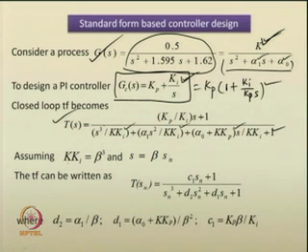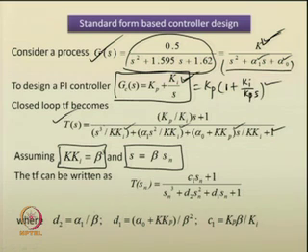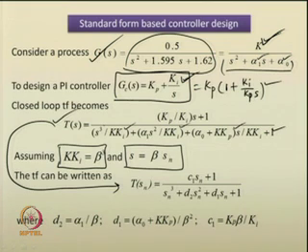So, the closed loop transfer function can be obtained in this form. Now, assuming k Ki equal to beta cubed and setting s equal to beta s_n, the above transfer function can be expressed as T(s_n) equal to C1 s_n plus 1 divided by s_n cubed plus d2 s_n square plus d1 s_n plus 1, where d2 equal to alpha 1 by beta, d1 equal to alpha 0 plus k Kp by beta square, and C1 equal to Kp beta upon Ki.